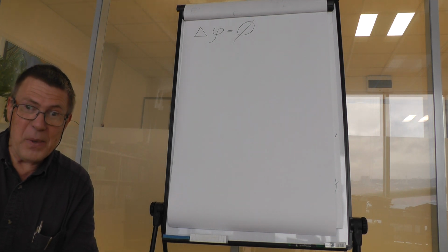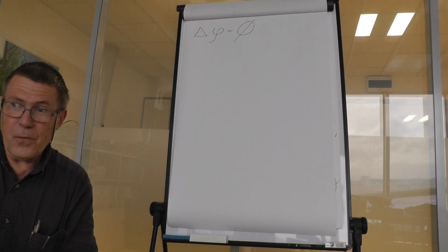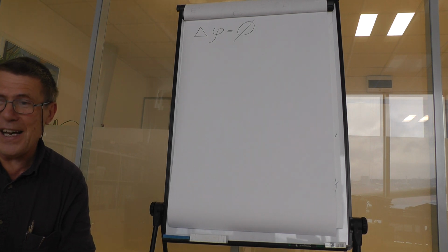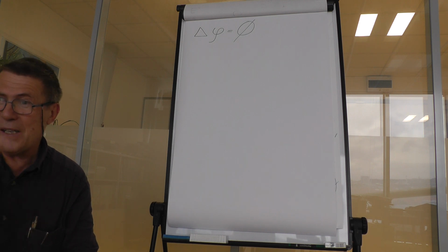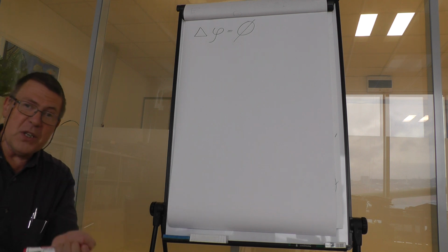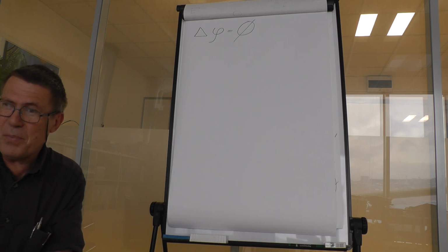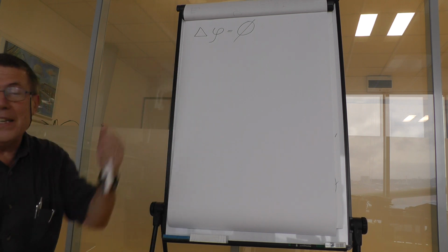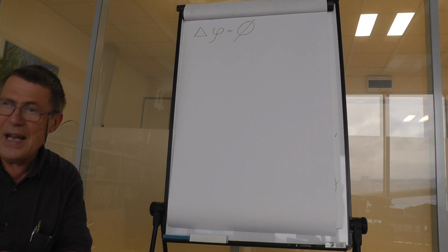We have even been using, for 2D problems, paper that was conductive, and we glued aluminium electrodes on it and just measured the distribution with a voltmeter, which is now a museum type of exponent, because there are numerical methods for solving the Laplace equation.